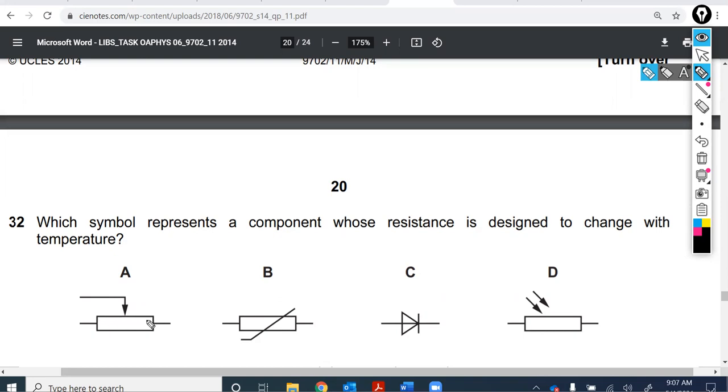It acts just like a metallic resistor. You can just adjust how much of the metallic resistor that the charge is flowing through, right? And so we've talked previously about an equation for resistance based on what metal it's made of, its resistivity, the length, and that's really the key here. As we increase the length that the charge is flowing through, there's going to be more resistance, right? Because the area of this is staying the same. So this is the equation for resistance in terms of its resistivity, the length of the metal, and the area of its cross section, usually a circle for cylindrical wires.